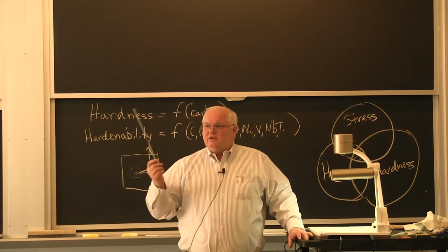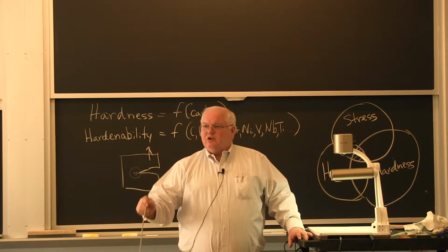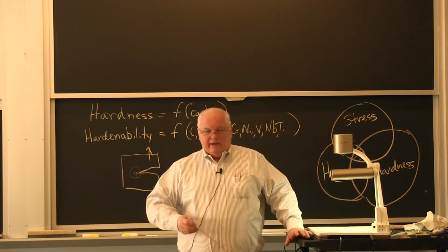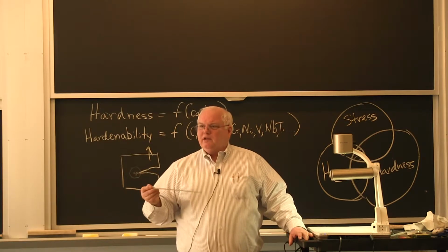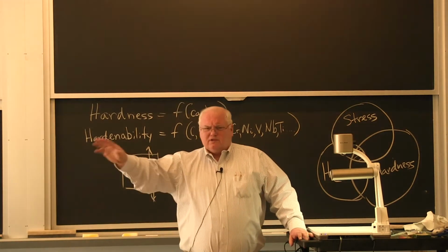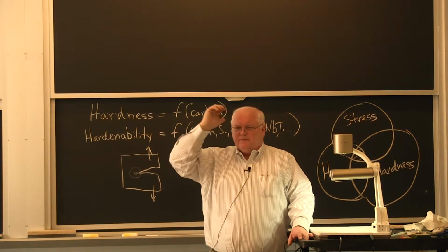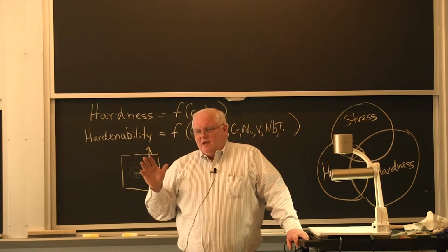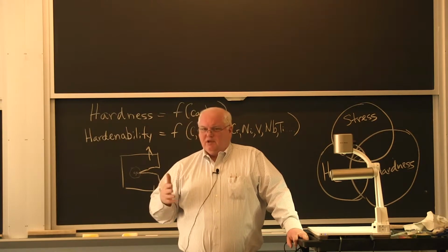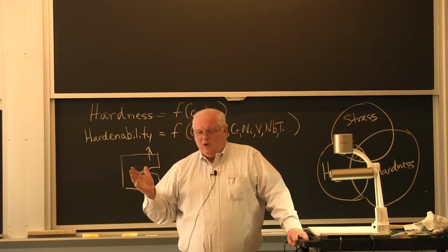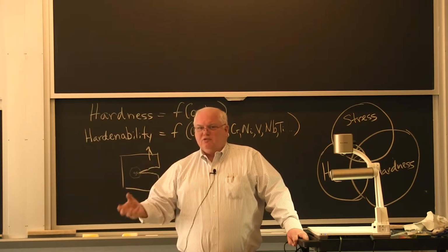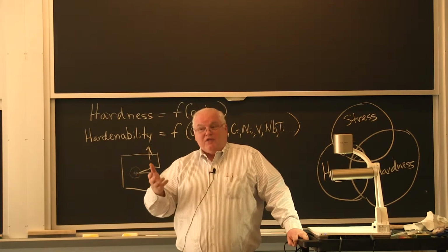A guy in Göteborg, Sweden, found sticking his bare electrode in the mud at about 1910 and welding with a muddy electrode excluded all the porosity that came from welding in the air, in terms of the nitrogen in the air causing porosity. I go through this in my fusion welding class, okay, in a little more detail. But anyway, that in Göteborg, Sweden, that became the beginning of what's now known as the ESAB company, which is one of the world's largest welding companies. But they learned to use muddy electrodes. They were basically using minerals from the mud, okay? But they had a lot of moisture.